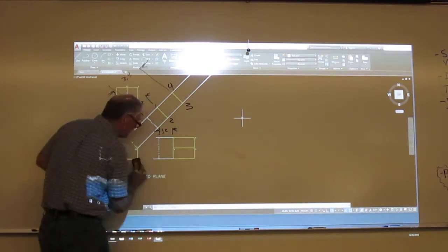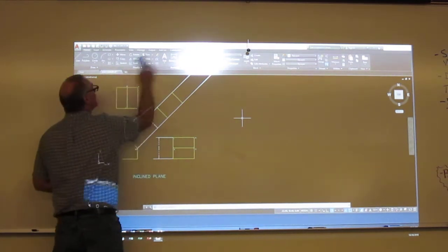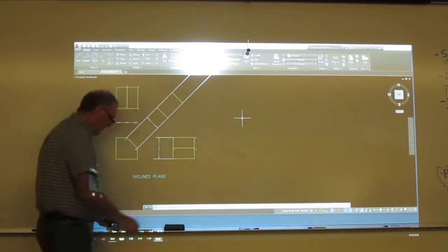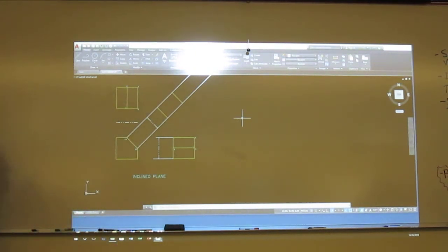Now, when we do auxiliaries, like we talked about yesterday, we're in essence really going to just invoke the partial convention, because everything else is described by my orthographic views. And so at this point, I'm just going to come in and clean this drawing up. We'll trim off that, get rid of these two, get rid of all this.